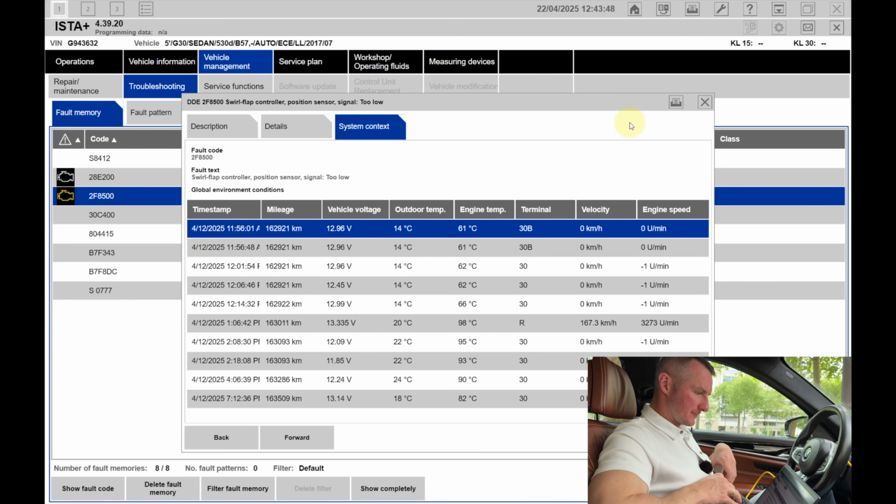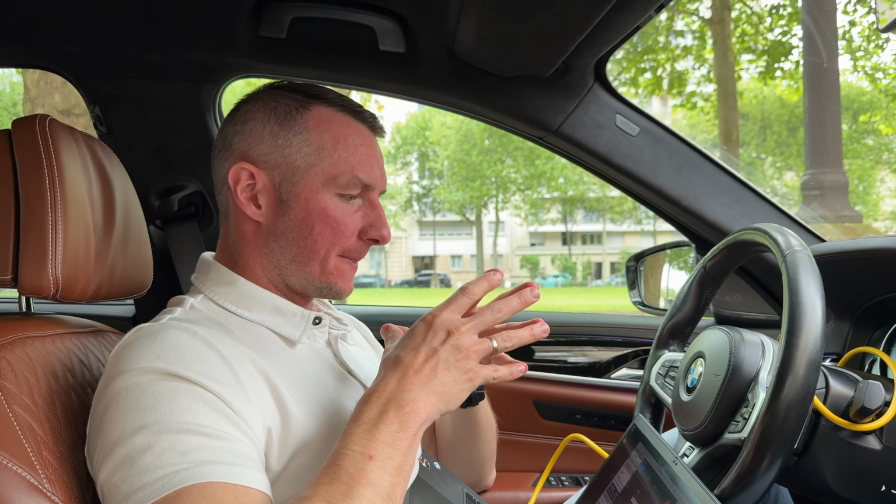Let's make the conclusions. Because this is my vehicle and I'm working with it, I have deleted all the errors to understand when that error starts. Of course, if you have never deleted any errors, you will have a way longer error history. You have to understand also that deleting the errors is not fixing the issues. If the errors are physically present in the vehicle, just deleting those will not fix your car. It just sometimes helps to understand.